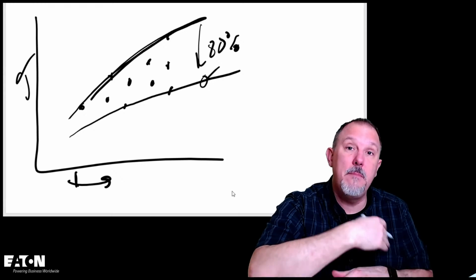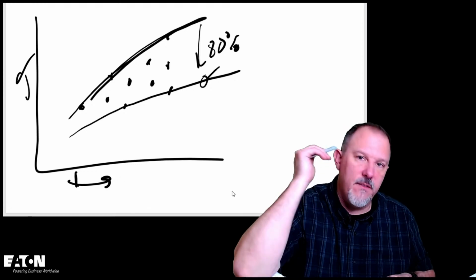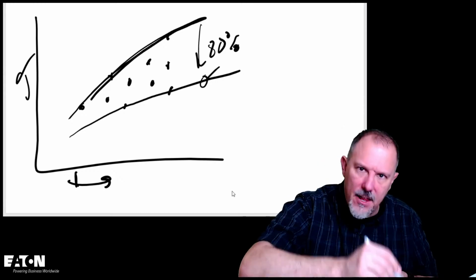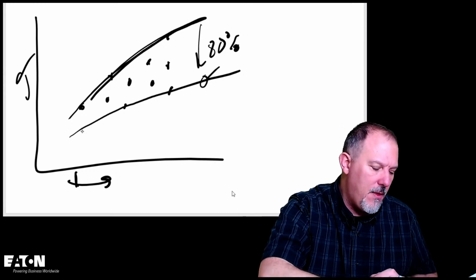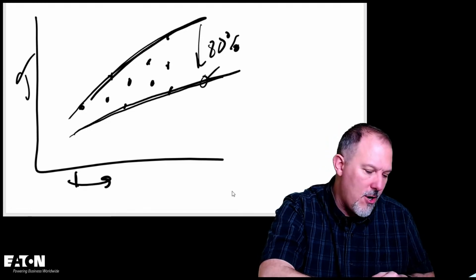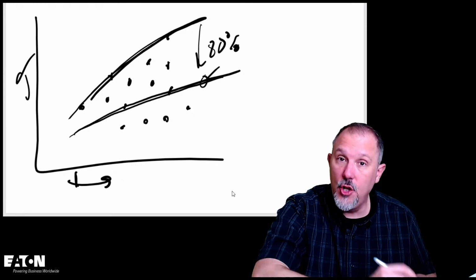Why? Because we wanted to make sure that, based upon all the data points of arc after arc after arc, the minimum arcing current that you calculated was not, you didn't have data points below that value, right? You want to be conservative.